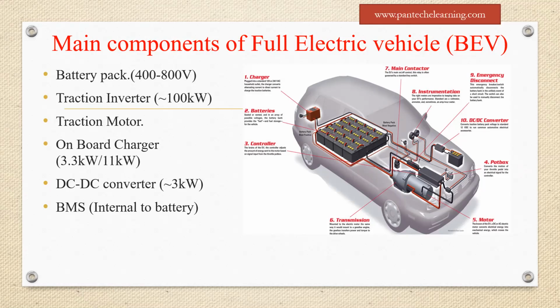Then for one time if you need to charge this 40 kilowatt hour battery, it will take between 20 to 40 units of energy. Then you can see here 20 units of power, how much cost you can estimate. If you are traveling from Chennai to Madurai, more than 6 hours of journey, right? Then how much fuel you need for a petrol vehicle or diesel vehicle, according to that you can fix how economical it is.